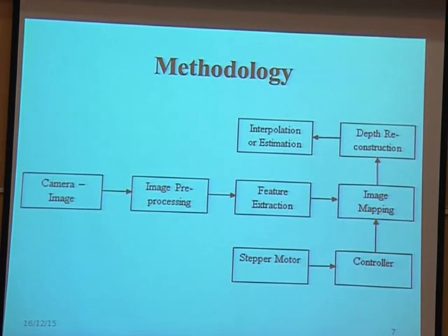The basic problem in color thresholding is that the color of an object changes from object to object, so we cannot change the threshold value every time. For that, we project a light behind the object so that we get the threshold value near zero, near black values. So this will solve the problem of thresholding.